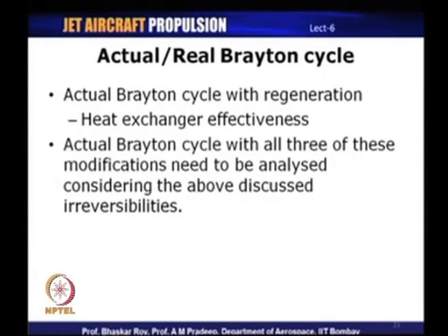Now, with regeneration, let us say the above cycles are being used with regeneration. Regeneration, as we know it, is basically a heat transfer process. So, heat exchanger effectiveness will also have to be considered during an actual Brayton cycle which operates with regeneration.